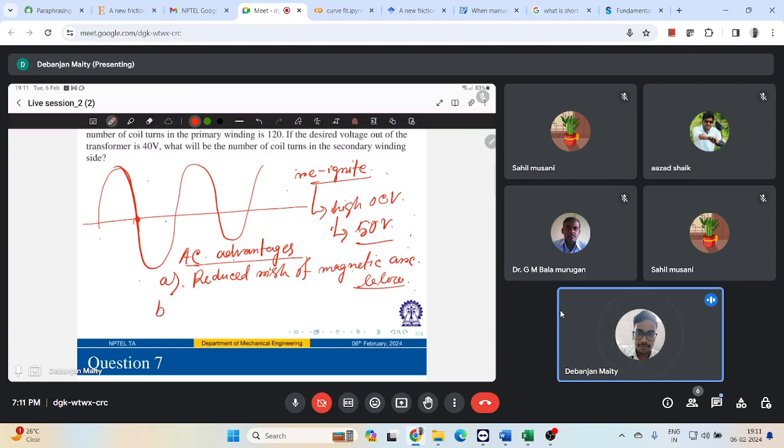And also, in general, people use it for oxide breaking performance. So always you will have surface oxides on any kind of metal surface, and AC is very useful to break those oxides because of its alternating nature.